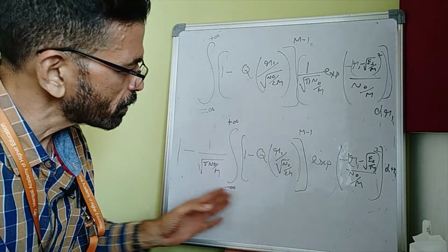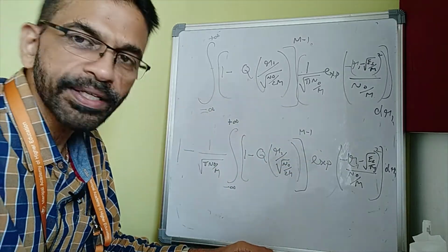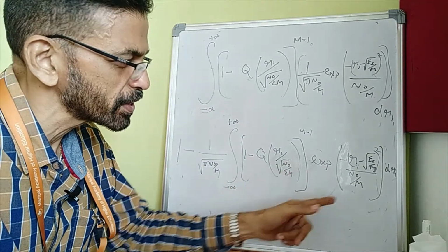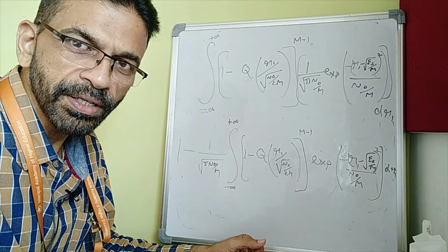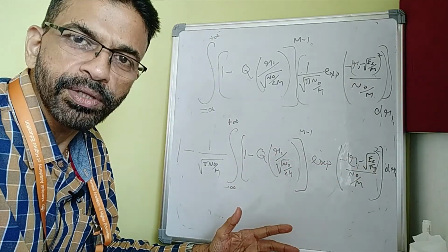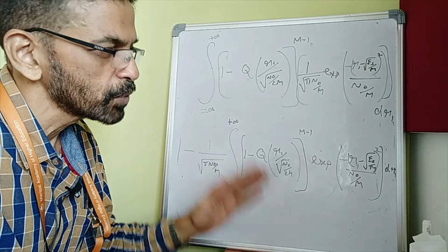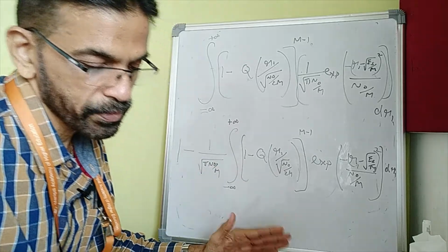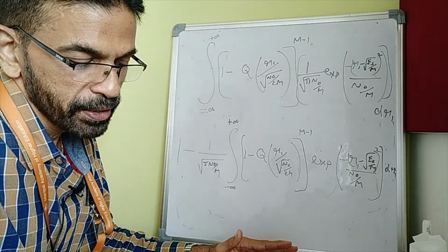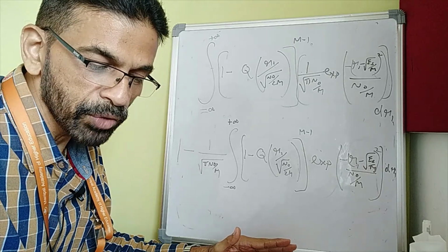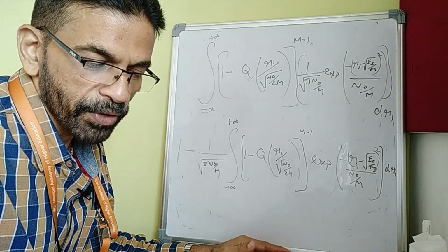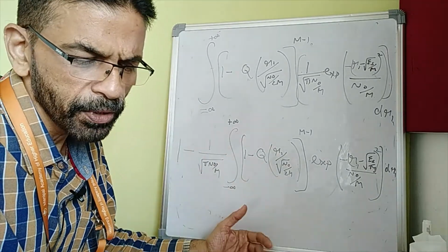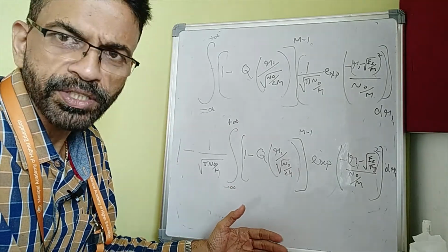So though we have arrived at this result by taking a specific case, S0(t), as the transmitted signal, you will end up getting exactly the same result, with a minor difference wherein R1 will be something else. That's all. You will get exactly the same result if you had assumed any other signal to be the transmitted signal. Now this means that, and it goes without saying, the assumption is that the symbols are equiprobable. In the case of M-ary FSK, you have M symbols and M signals corresponding to them, and the probability of any of these symbols being given out by the transmitter is 1 by M.